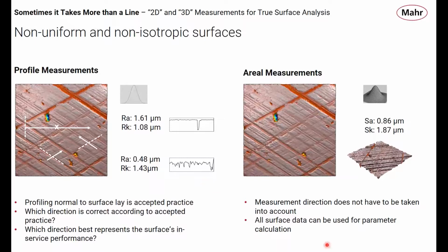The big advantage to areal, specifically for surfaces like this, is we can force ourselves to catch all of the data. That Sa parameter represents all of the hone marks, even the pits that are in the surface. Again, there's another webinar there. If Mark Malberg were here, he would probably have some words for me on this topic. But the idea is we can use this Sa to capture all of the data in that surface that represents our roughness. So that's a big point here.